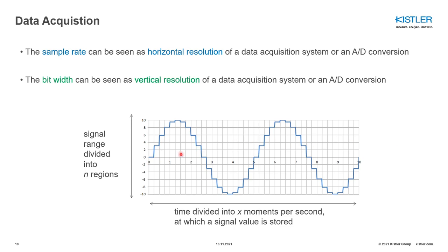As you can see here, a physical happening, a true signal, is in a sinus form. You can see those rectangular meshes here, and the horizontal resolution is actually the time that passes between each sampling. So we are trying to make a sampling, and the time step is the horizontal part of the rectangle.